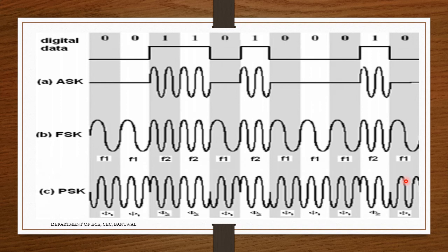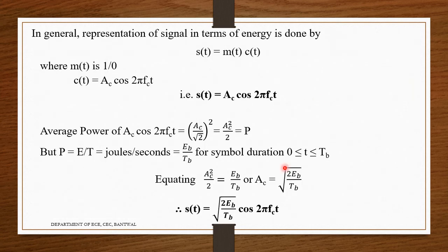What I explained theoretically, I am explaining here with respect to the bits, with some random examples. So next one. Here the transmission of ASK, PSK and FSK has been represented with respect to one example, the data bit stream.